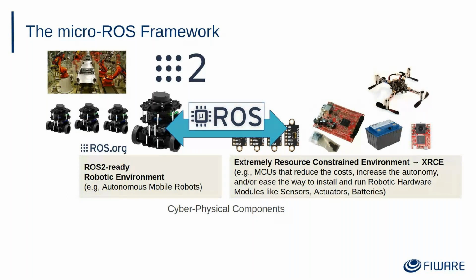And what micro-ROS is doing is going through the ROS architecture, solving every type of integration and enabling the traditional ROS APIs on microcontrollers. Then, relying on the DDS middleware, in particular the ones developed by eProsima, Fast DDS and Micro XRCE-DDS, the integration between the microcontroller environment and the ROS 2 ready environment becomes seamless through the standard ROS 2 interfaces.